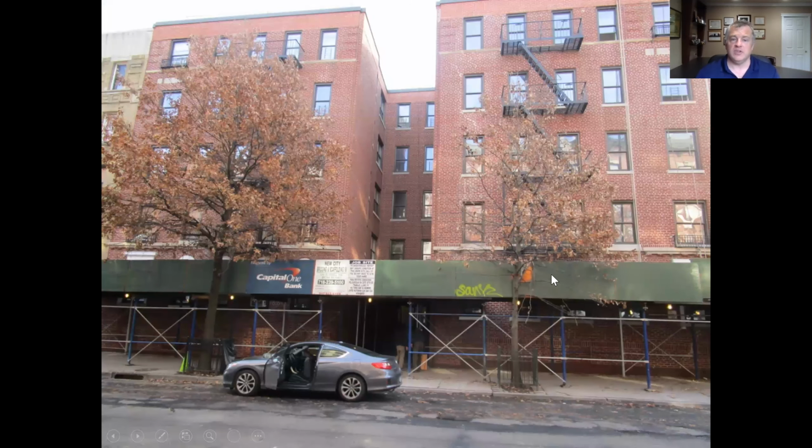Good classic 6-story brick tenement style building, flat roof. Looks like they have a sidewalk shed up, starting to do some work. We see our fire escapes out front, our second means of egress. Most of the time, those 2 windows will connect 2 different bedrooms and supply that second means for that apartment. And then the primary means would be the apartment entry door. However, you do see some buildings still to this day that have 2 apartment entry doors from the hallway, and that's their second means.